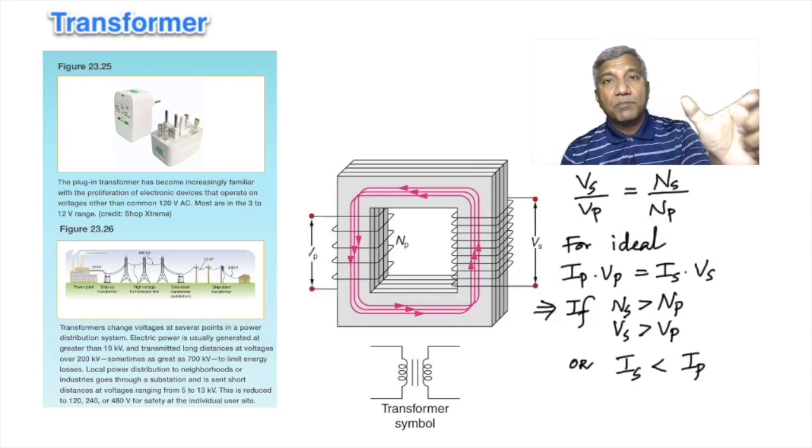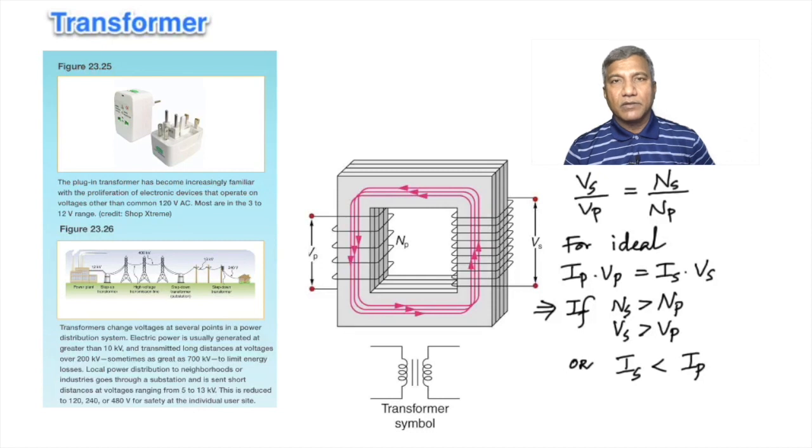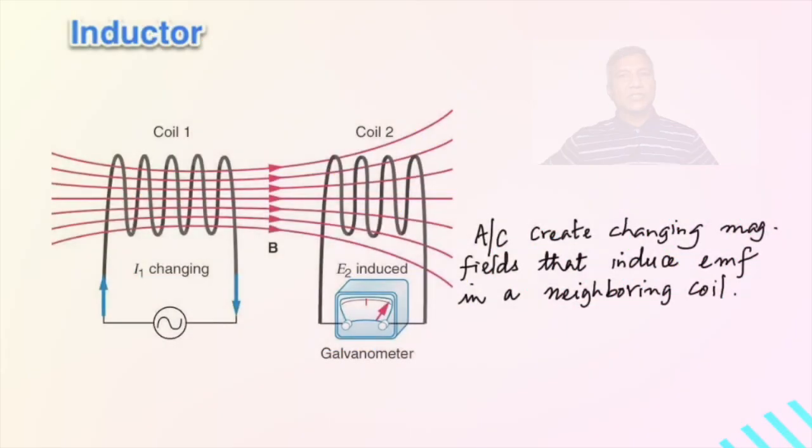That's a step-up transformer, which again means the current in the secondary is going to be less than the current in the primary. So that's why I said at the generating end, you use a step-up transformer. Why? In order to have a smaller current on the secondary, which is going to flow through those cables.